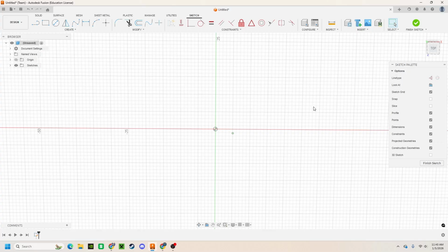It is important to consider that all of the constraints define some aspect of a sketch body. For example, coincident constraints can be used to define a position, since it pins a location to another object. Parallel can then define an angle, and equal can define a length. Therefore, using these constraints, we can define every part of a sketch.